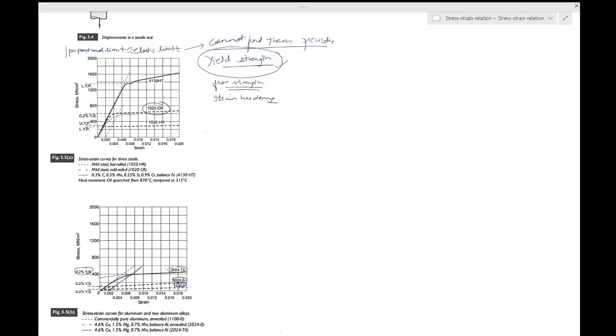So obviously this curve is quite complicated, but is it reasonable if I idealize this behavior as this, which is elastic plastic without strain hardening? Okay, so this is an idealization I would want to make.